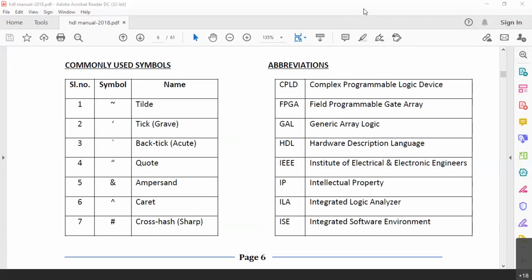In Verilog, we have a built-in library. That is why we don't specifically say it in the program. But in VHDL, we use a library called IEEE, and in that library, there are multiple packages. We will be using whichever packages are applicable to our program. That is how the programs can become more compact.